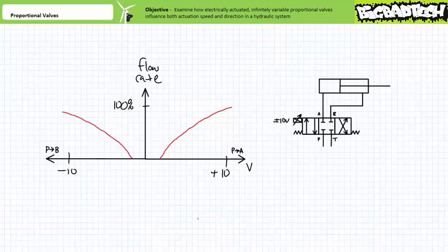This may seem counterintuitive to those of you that are versed in flow rate and volume calculations. However, it shouldn't be, because remember that flow rate through a restriction, like a regular flow control valve or a fancy proportional valve, will be greater given a larger pressure differential across it.